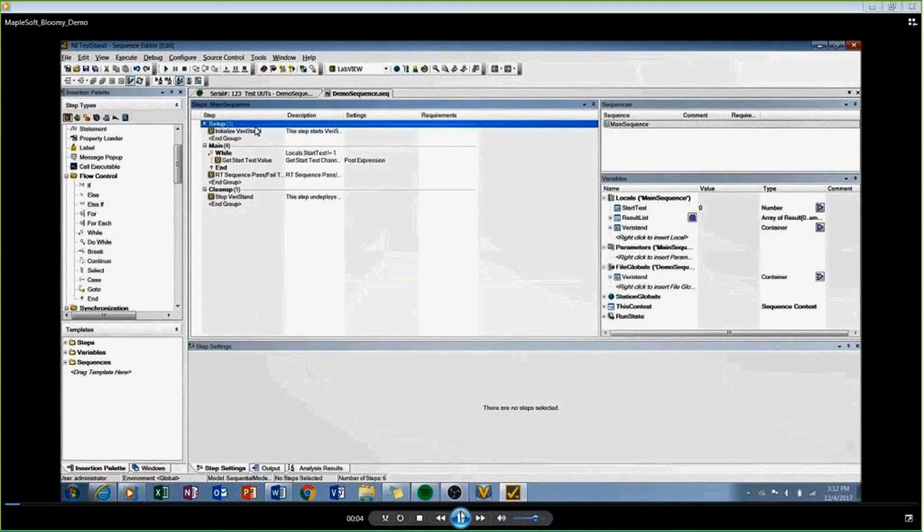If I click this, basically, TestStand will initialize VeriStand, open all the necessary project references, and run the configured project. It enters this loop where it's looking for whether or not the user started the test, and once it does that, it'll go into a real-time sequence. This real-time sequence is just a CSV file that is right now mimicking the signals that a BMS would produce. We don't actually have a BMS to use, so right now it's all simulated signals that are being mapped to the model.